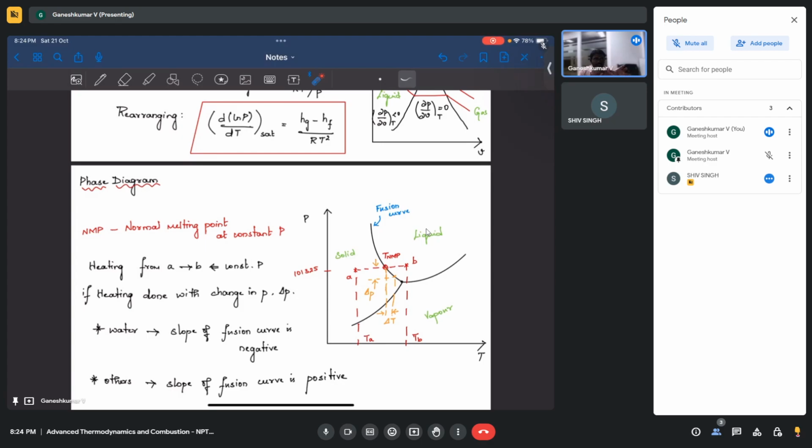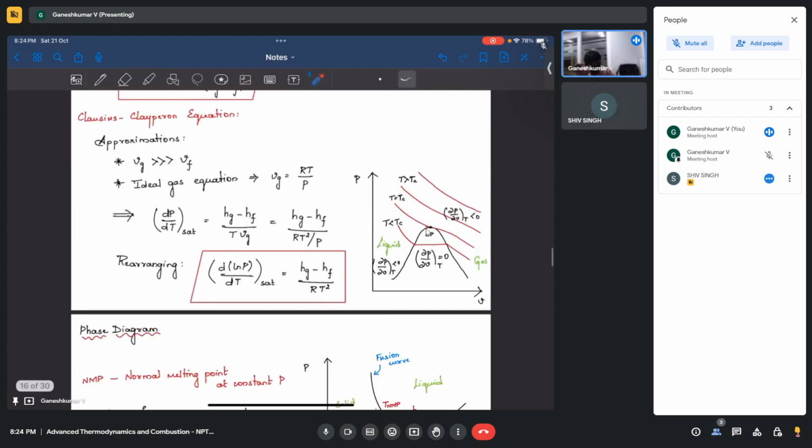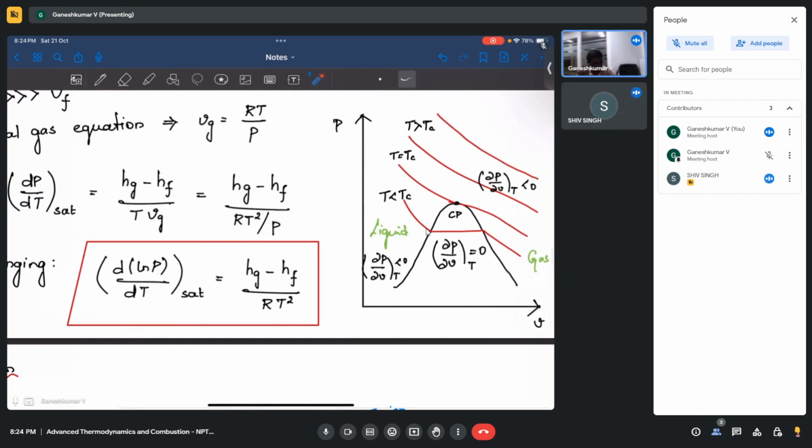But for other states, let's say if your system is a phase change from liquid to gas, then I will have one degree of freedom. The reason is I can change the saturation pressure or saturation temperature, right? So if I increase the saturation pressure, the temperature automatically changes. We are not changing the temperature, right? So a phase change system has one degree of freedom, like either pressure or temperature. But the triple point doesn't have one degree of freedom. It has only zero degrees of freedom, which means you cannot change P and T. It exists in only one particular P and T.